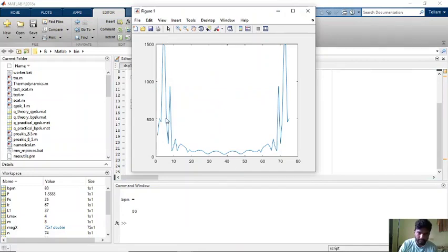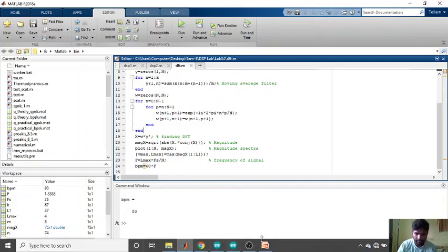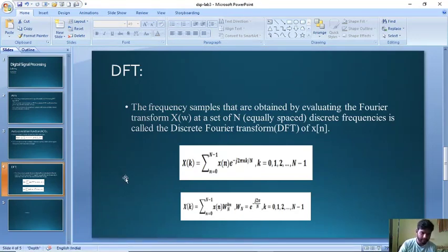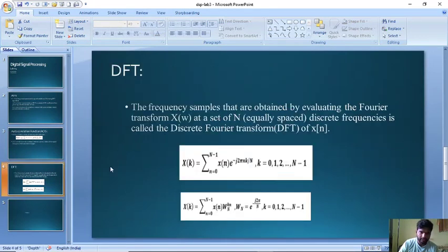These are the two dominant frequencies, and this is the BPM. We got the BPM as 80. As I said, there is an error when we compute the BPM using Arduino and MATLAB, and there is an error between the procedures, like we computed using DFT and using the autocorrelation method, but there is an error of about 20 between the procedures and the software.